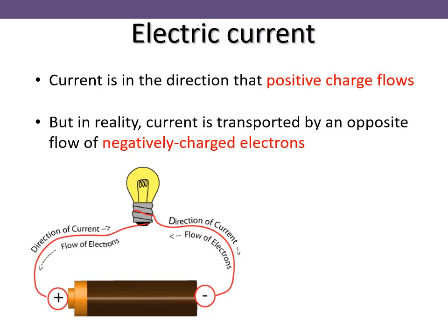In only very rare situations, or if we're just trying to assess whether you actually understand how electricity really works, will you ever be asked about electron flow current. So please don't get confused between conventional current, the direction a positive charge would flow through the circuit if it was free to do so, and what's actually happening, electron flow current.